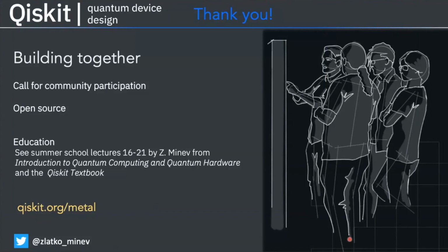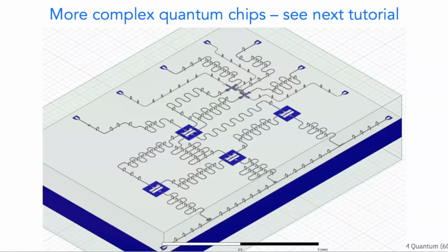Great. Thank you. That's a good question. So materials: you can specify any material you want in the properties of the transmon qubit. That material has to exist. You have to define it, or we can add it to the simulator. So for instance, here, I think this chip is sapphire. You could choose it to be silicon. You can define your custom material as well. So it's quite versatile in that way. I think materials is something that's still being developed, so it works, but there's probably some more room for things to grow. So if you have more detailed questions, maybe ask us on the Slack channel.